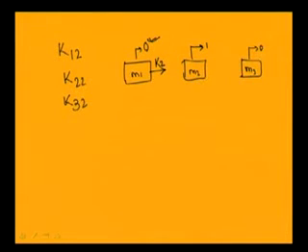To prevent this motion of mass 1, or to have 0 displacement of mass 1 when a force K2 is acting on it, one has to apply a force F1 to have 0 motion here. So, this F1 equal to K12. As this is acting in the opposite direction, I can write K12 equal to minus K2.